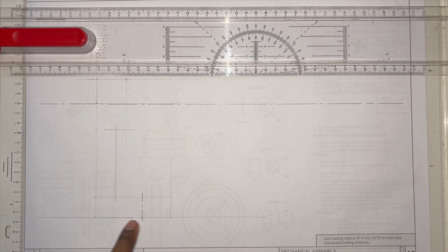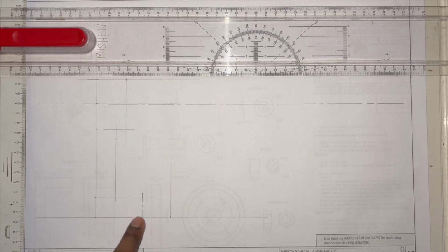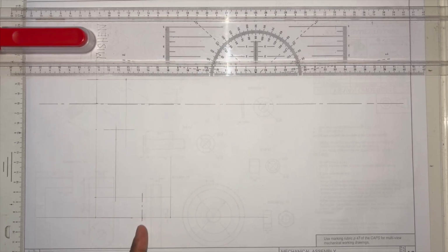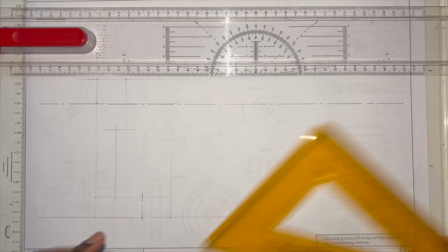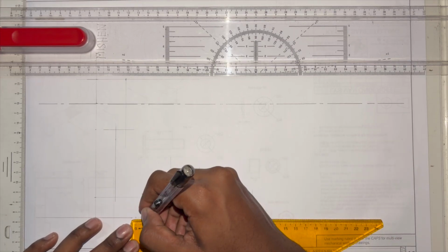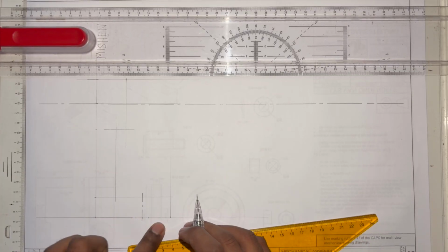I need to draw that circle that's here. There's a hole that we are cutting through. Sometimes you don't cut through a hole, but you just need to make sure it is in the center aligned. Then you cut through it. Now, they're telling me it's got a diameter of 12. If it's got a diameter of 12, that means it's got a radius of 6. So I'll have 6 there and 6 to the right.